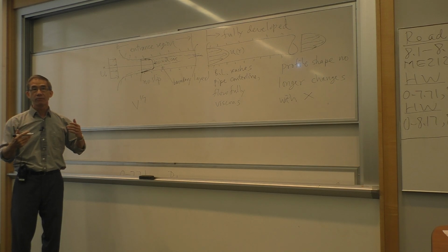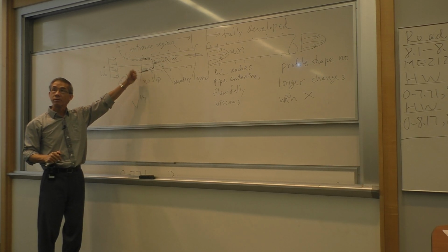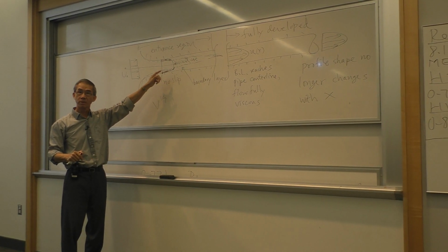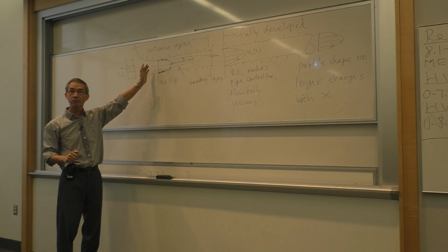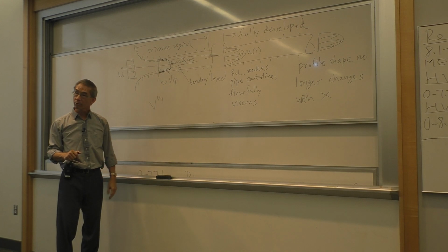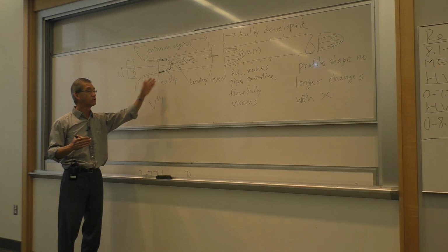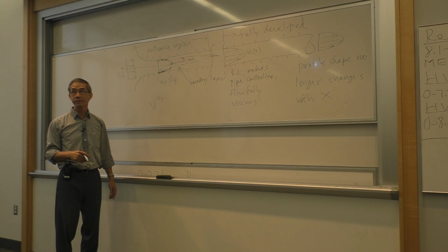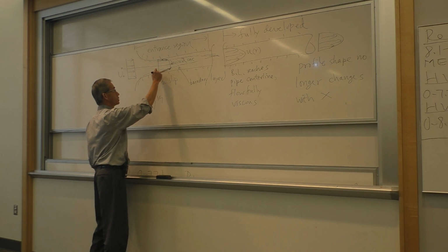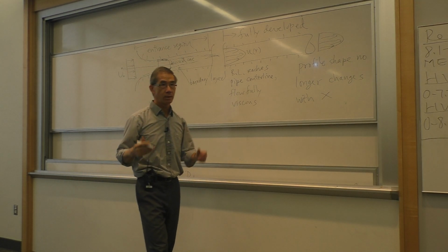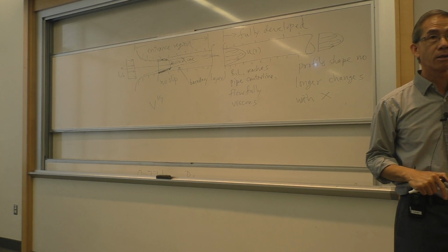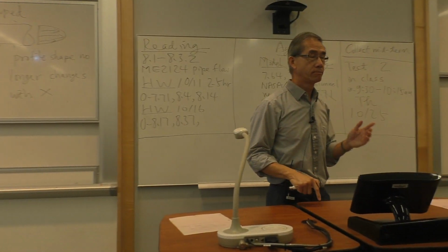It becomes now a very peculiar condition of the Reynolds number. For the shape of this velocity profile, you have to tell me more information, like the Reynolds number. Then I can tell you from previous experiments what that profile looked like. It's anything but uniform. At this level, that's what I want you to remember. And in some cases, for simplicity, we assume it's linear, which is a simplified version. But as long as you remember it's not uniform, I'm happy. Whether it's linear, parabola, hyperbola, that's detail.